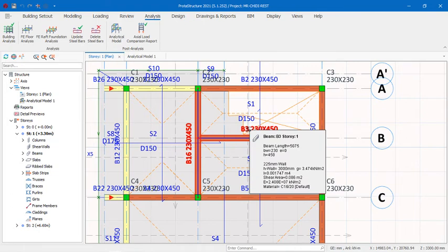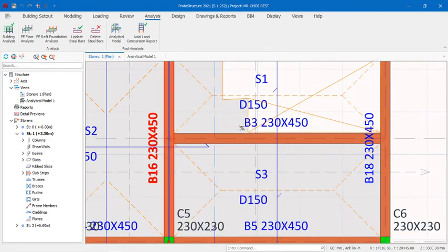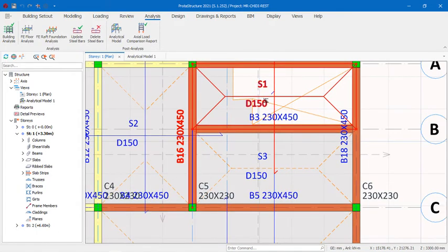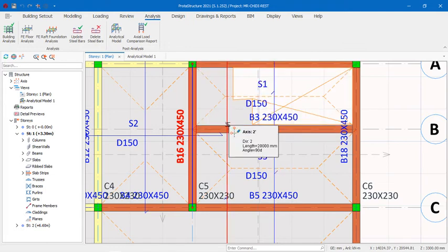Which is also advice for us as engineers. By the time you are loading your structure, especially if you are doing a high rise building, always go around and check the reaction of your structural elements as you are loading it.